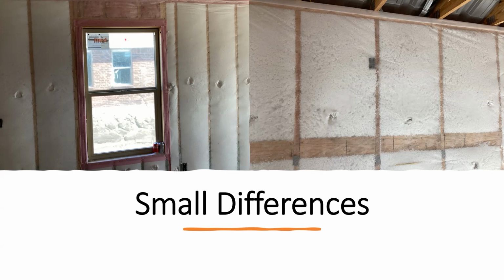Because you see a lot of the dark patches in between, a lot of the gray areas, that's a dead giveaway that it's not fully compacted and densely packed like it is on the left. So if you use an open hand and press against the cavity, you should feel resistance on the one on the left. It can sort of rebound.